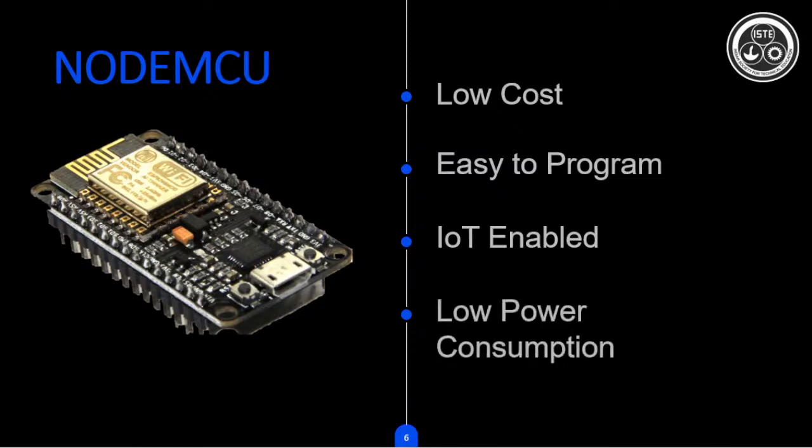As I said before in the things definition, this NodeMCU consumes around 76 or 80 milliwatts at 3.3 volts. At 5 volts, because you will be using a USB cable or USB adapters from your laptop, from wall charger adapters or travel adapters, which will give you an output voltage around 5 volts. So when you power it with 5 volts, and at max it will consume around 80 milliamperes, the power will be around 0.3 watts, something like that. Okay, 0.4 watts or 0.45 watts or 0.3 watts, something like that.